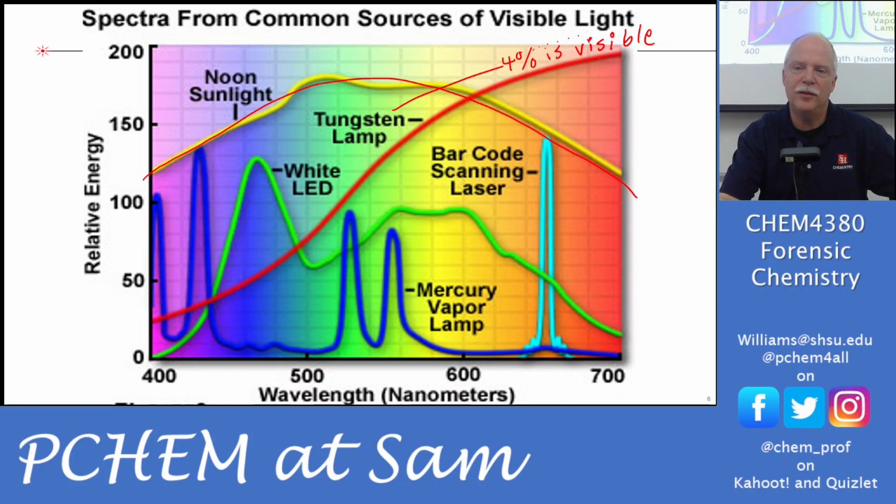That's why we've been pushing so much to get away from tungsten filament lamps or incandescent lamps in lighting, because they're just so inefficient. Think about that. You're buying 100 joules of energy from the power company, and you're only getting 4 joules of light. So you're throwing away 96 joules that you paid for, okay? Now, they're pretty cheap. A joule's not much energy, but it adds up, okay? And lighting can be up to between 5 and 9% of your household power costs. And so you know, if you lived in the dark the whole time, you might save 10% of your bill. But still, it is pretty wasteful.